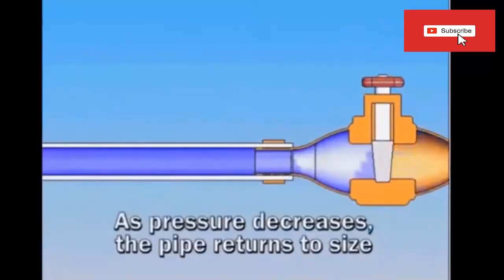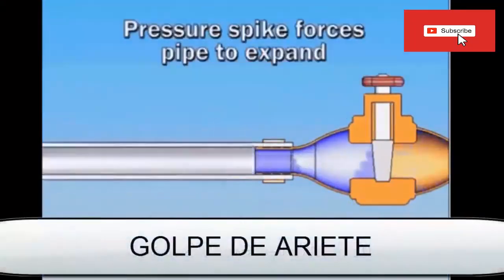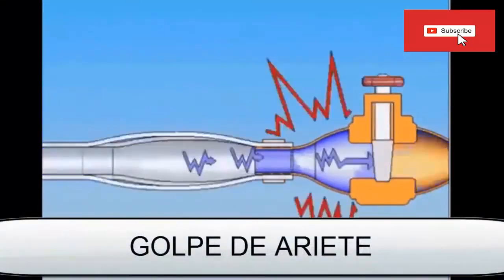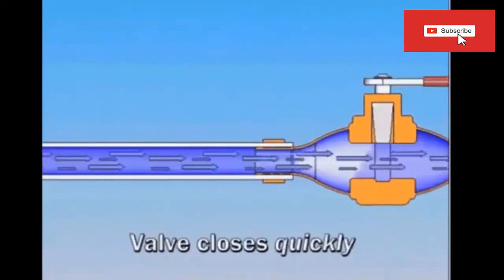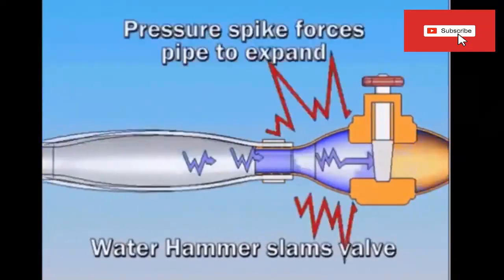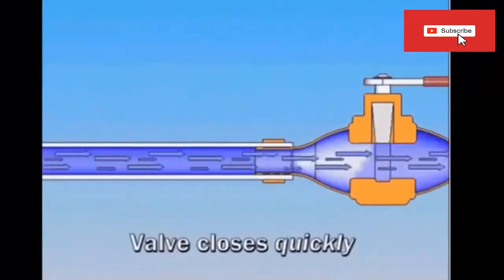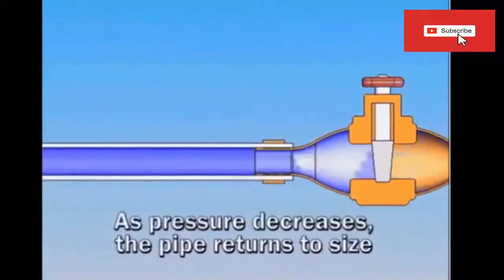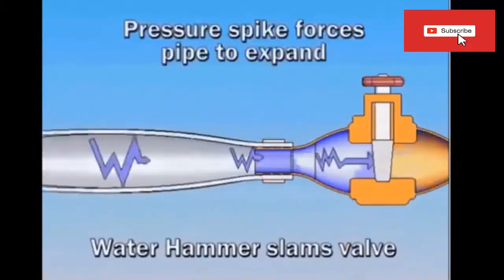Another thing to know about centrifugal pumps is the phenomenon known as water hammer. Water hammer is a sudden increase in water pressure that occurs inside the pipe when closing a valve or faucet quickly. The water hits the closed valve and bounces back like a wave. This rebound continues until the water hits an impact point and the energy from the water wave is more evenly distributed in the piping system.